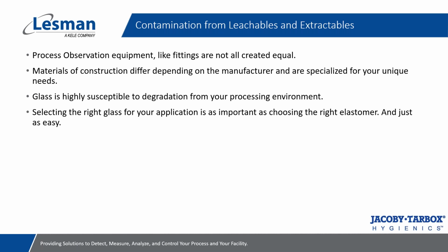And then the larger you go, as you get up to our top size, which is a 12-inch, I think we're still at 145, 150 PSI, which there is nobody on God's green earth that is putting 150 PSI into a 12-inch line. That's most of the time asking for disaster. So that does lead me to one thought I want to share, just because that's a great topic.